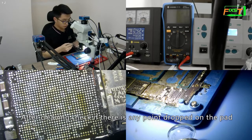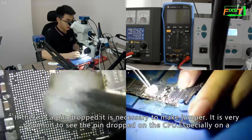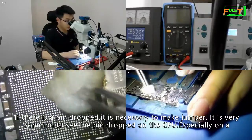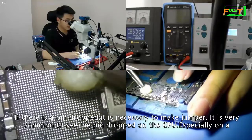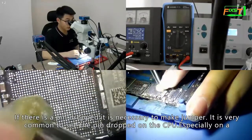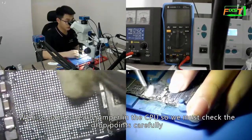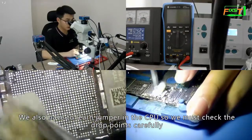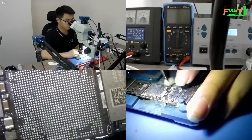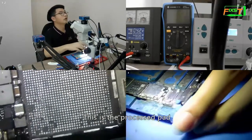After cleaning, check if there is any point drop on the pad. If there is a pin drop, it is necessary to make a jumper. It is very common to see pin drop on the CPU, especially on a phone that has been dropped. We also have to learn jumpers on the CPU, so we must check the drop points carefully. This is the processed pad.